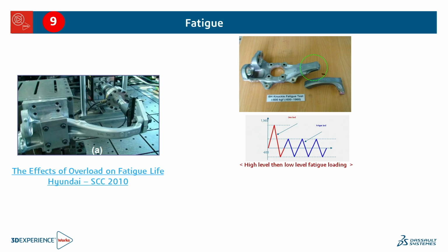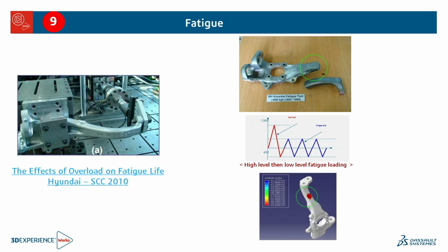However, they knew that this was not the case. They were testing these steering knuckles and they break in the arm. That is really tricky to explain just using finite element analysis. So that is why a durability analysis is very useful, because you're dealing with the fatigue damage, and we did indeed predict the failure will be at the arm in this particular load case, which is why they were talking at a customer conference and why those of you who kept your hands down were actually correct.